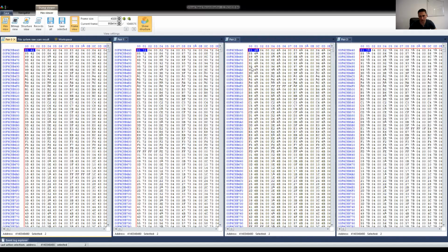Do you see which result was the first one, which pair is the next one, and so on? Now we just compare these hex values, and the minimal one will be the first one. Here we have 8162, 8172, 816A, 817A. The minimal one, I would say, is 8162. The next ones we have 726A, 77A. So this one is smaller than the others, so I would say that after pair 0, we have pair 2, right?